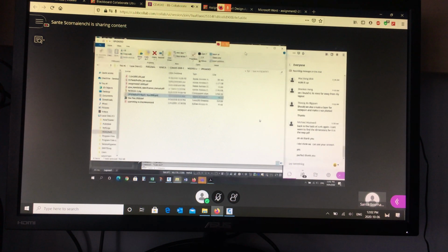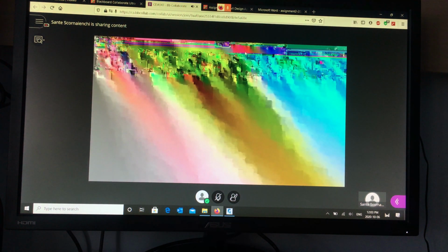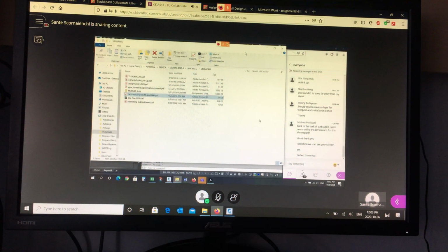Next semester, one of the tasks you have to do is keep track of the standards you're going to use, right? So as you look stuff up, keep track of which standards you're using as you work. Almost like a reference sheet of what standard you used, right? So what's the width of pavement in this case? 8.5. How do you know? Because of this standard, right? You have to be able to quote the standard. It's good record keeping. And then you have a short list of where to look for stuff next time you work in that municipality instead of the whole document.